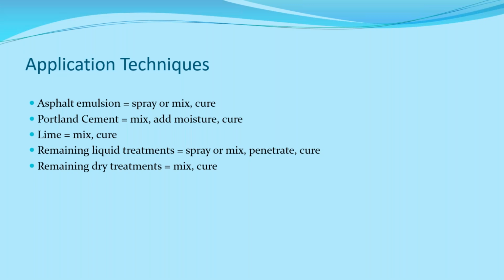Lime, I don't like lime. I've had one project with lime and it was a mess. As a matter of fact, we ended up having to shut down the job a couple of different times because of safety issues. It does work well, but it works well with a real high clay content. And it generally has to be mixed as a slurry. It's metered out onto the roadway as a wet product, and then more water is added and it's mixed in, and it performs about like Portland cement.